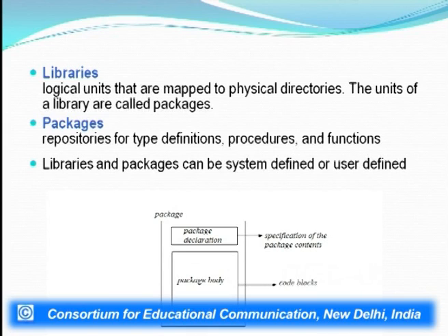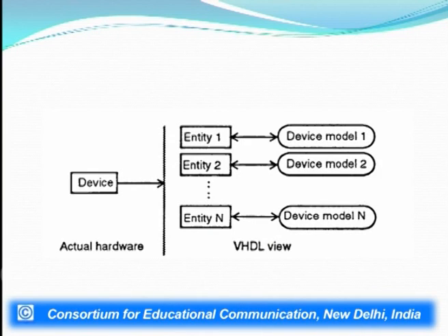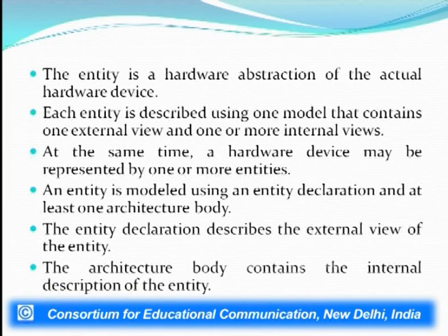So a package essentially comprises two parts. There is a package declaration which specifies the package contents, and there is a package body which introduces the code blocks for those contents for which the declaration has been given. Now this particular diagram shows the device, which is the actual hardware, and the VHDL view wherein the device has been broken down into different entities, and for each entity there is a device model associated with it which has been described.